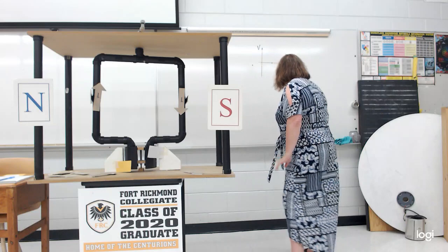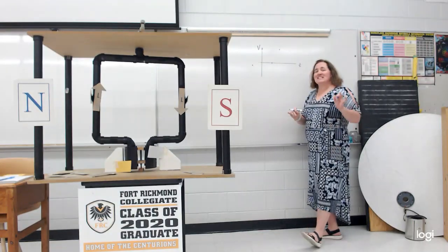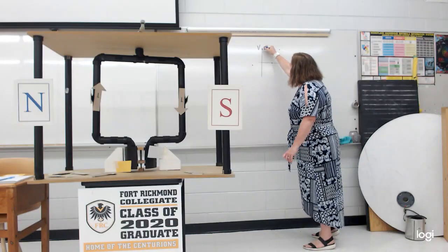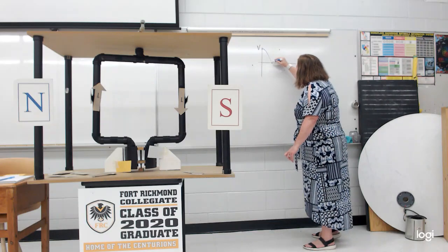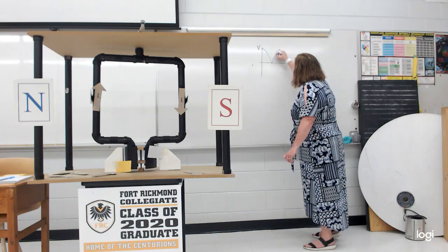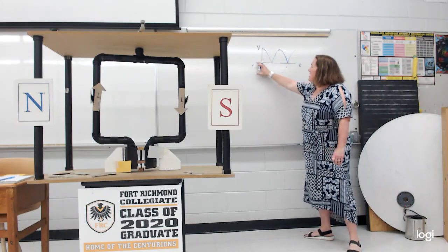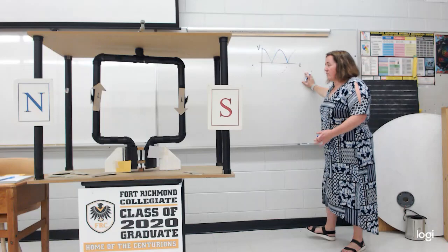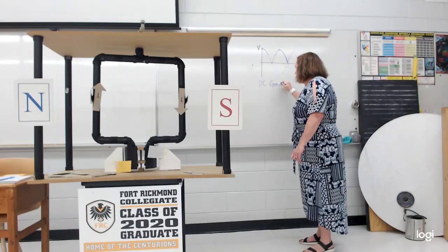So you'll notice that now the voltage would be in the same direction as before. So what has happened is our graph that used to look like this has now gone back up and down. I really cannot draw. And then it would keep going over and over again. So we've eliminated the negative. We've rectified the direction of the current, and we've created a DC generator.